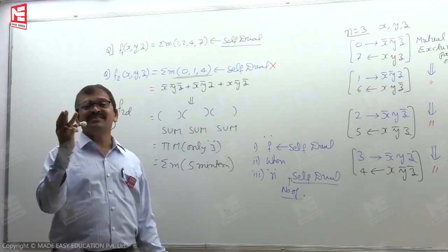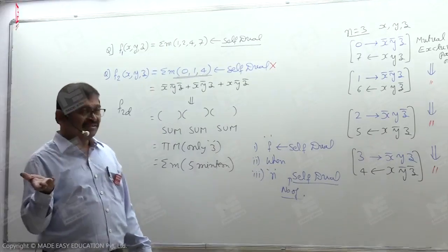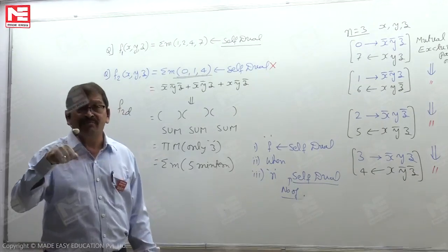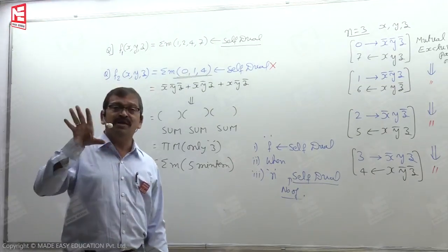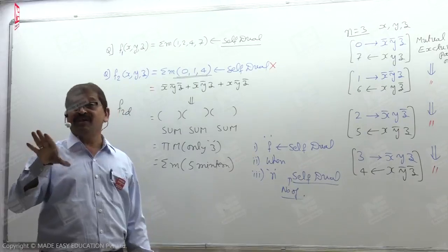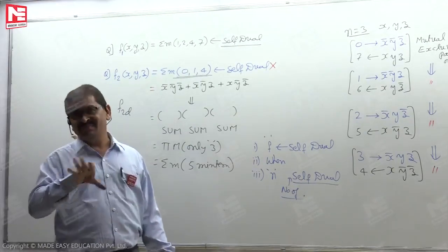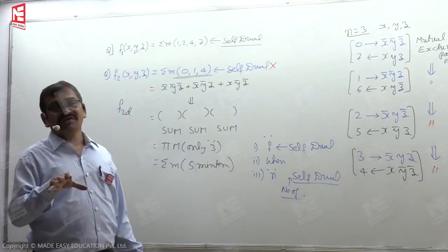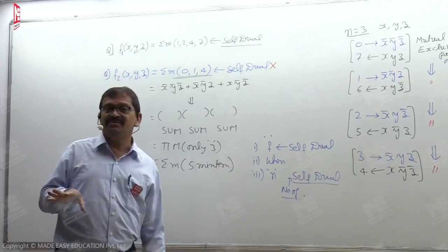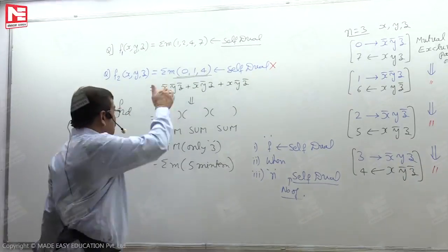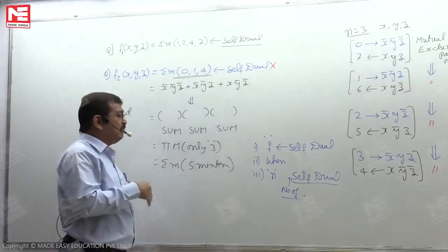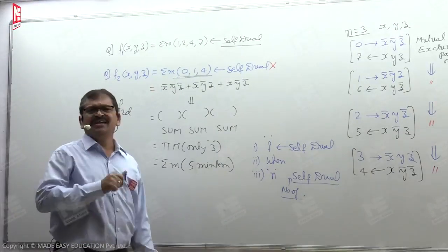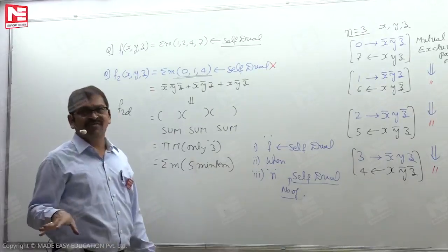On the 3 variable case, the total number of combinations is 8. Out of 8 combinations, as and when 4 combinations are the min terms, then there may be a possibility that the given function is a self-dual function, but it is not guaranteed to be always. We'll see why. But when 4 combinations are not the min terms, something like 3 combinations or 6 combinations or 2 combinations or 7 combinations, you can discard it by default without any sort of work.